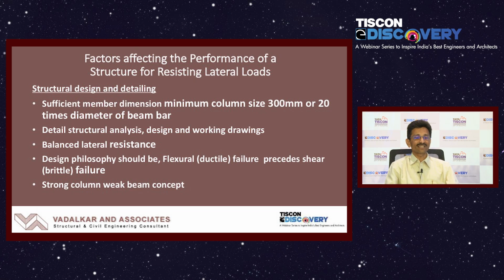So detailing of the structural members is also very, very important. Detailed analysis as well as detailed drawings are required to get good structures. And you should have balanced lateral stiffness. We need stiffness in both directions, because we never know how the earthquake is going to occur and in which direction it is going to come. So we have to have balanced structural stiffness, or resistance as we call it, in both orthogonal directions.